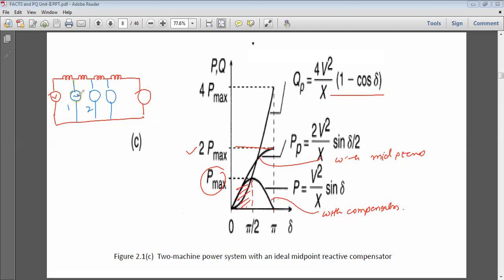But when connecting a number of shunt compensators, all of them have to be synchronized very well, otherwise it does not give proper operation. Second, such synchronized control increases the cost of the system.